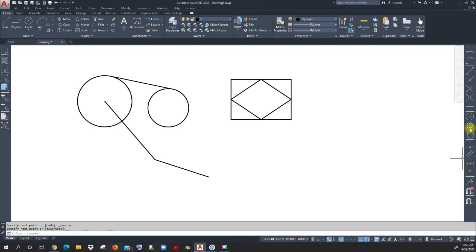These will only work when you're in a command. If I click snap to tangent now, my command line says, I don't understand what you're trying to do. So anytime I click without being in a command, it's unknown command. It doesn't know what you want it to do. So you have endpoint, you have midpoint, which we keep on all the time. Center point we keep on all the time, but you have options for the quadrant, tangent, perpendicular, parallel, the nearest, or the insertion point, or a point. So there's lots of object snaps that we can use whenever we need them.